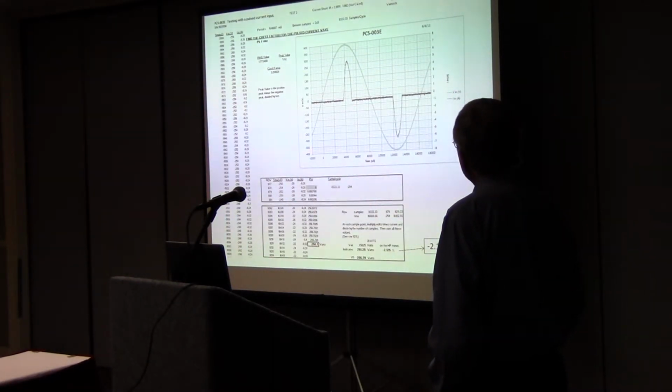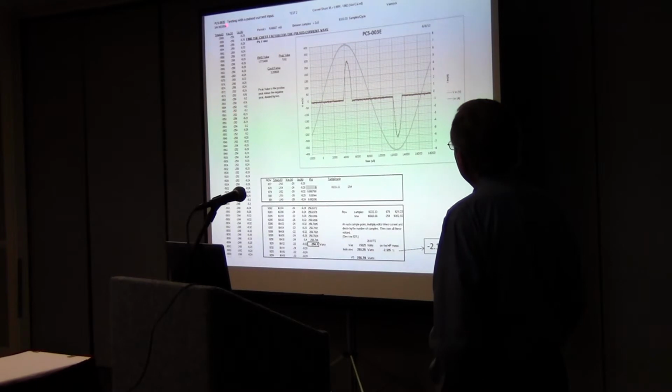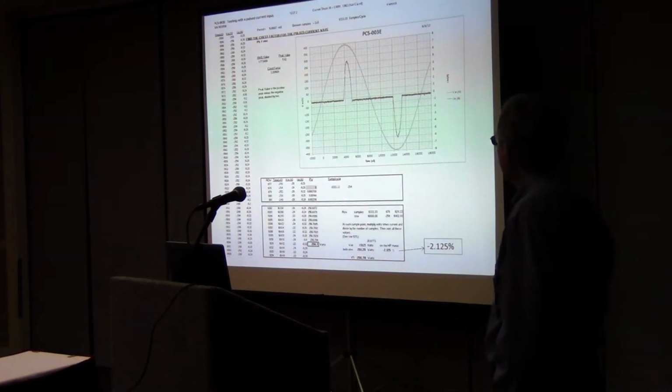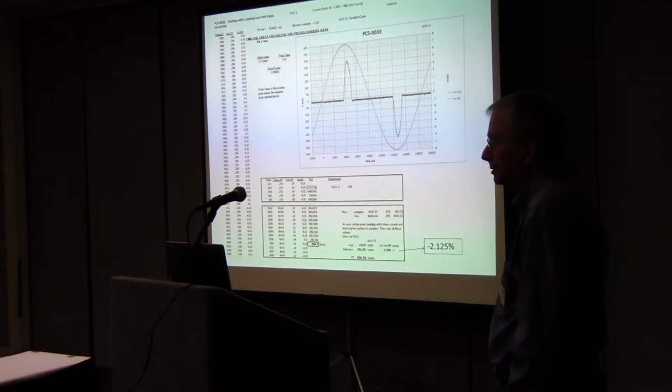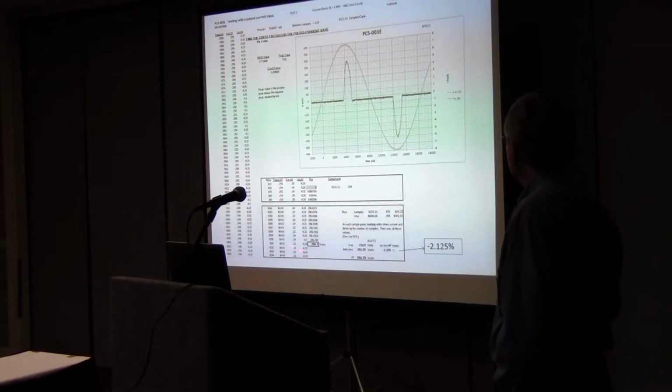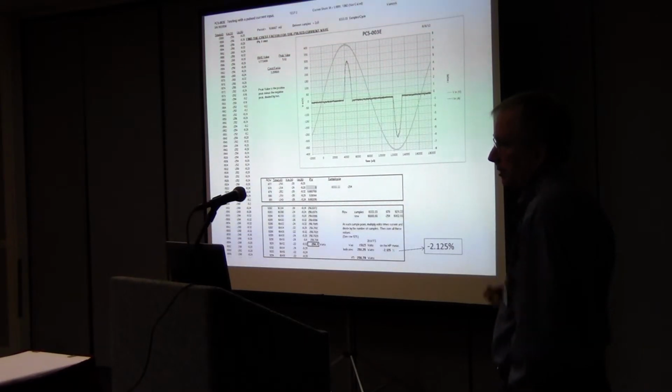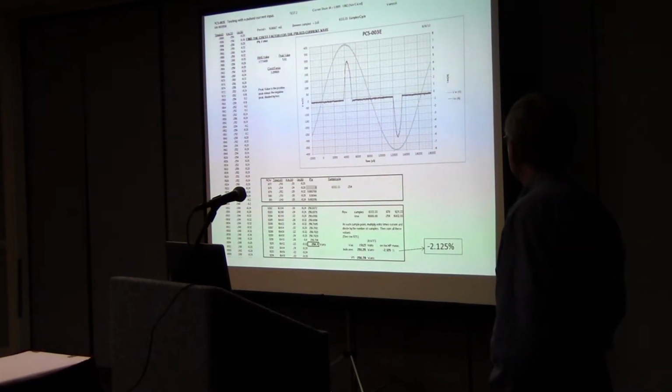And again, we put both of these waveforms into Excel like I was telling you could do, and we just did a point-by-point multiplication in Excel. That said we should, with these two waveforms, see 256.7 watts. So that was just an Excel calculation based on these waveforms.